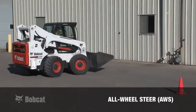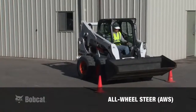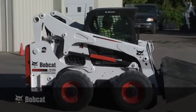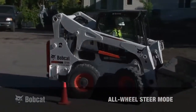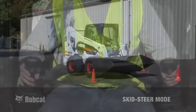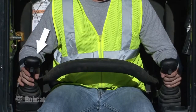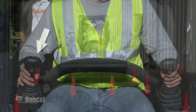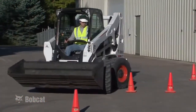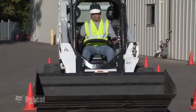The Bobcat all-wheel steer, or AWS loaders, also provide joysticks to control drive, steering, lift and tilt functions. The operator can select between two different steering modes, the all-wheel steer and the skid steer mode. Regardless of the steering mode selected, the left joystick controls drive and steering functions, while the right joystick controls lift and tilt functions. When in AWS mode, you get precise steering from the coordinated action of all four wheels. If high range speed is selected, only the front wheels provide steering.